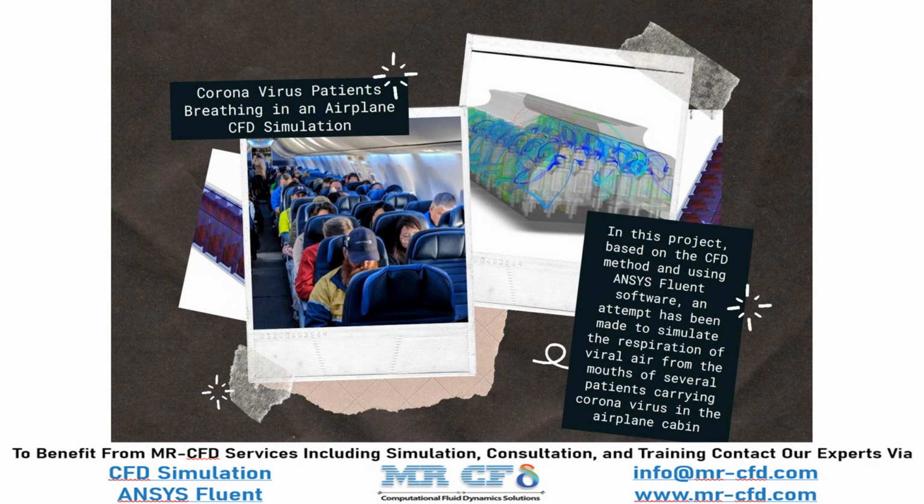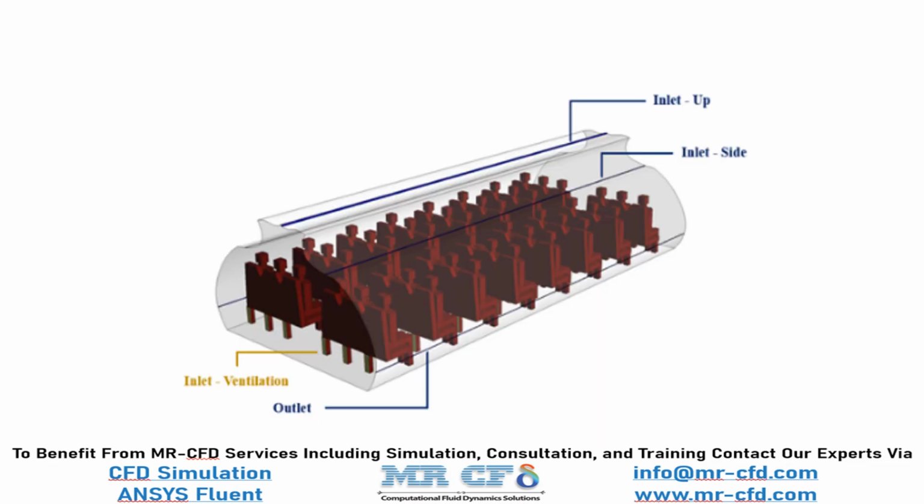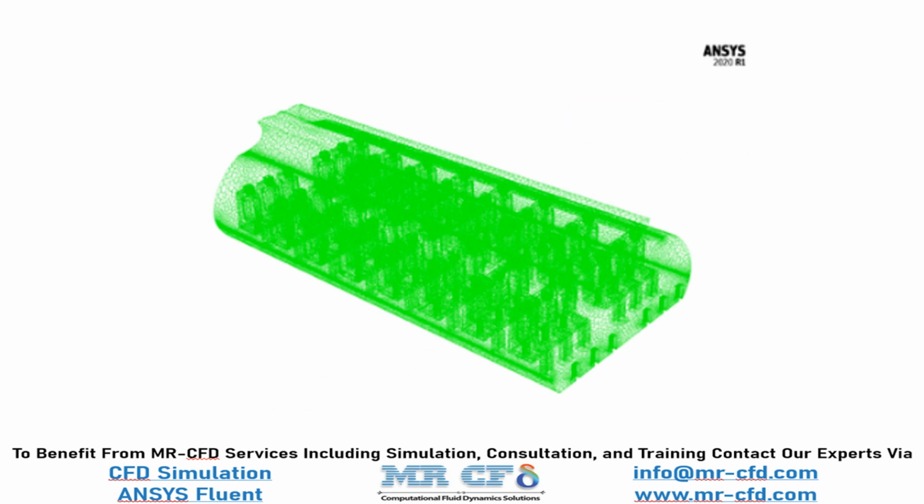We will simulate coronavirus patients breathing in an airplane using ANSYS Fluent software. The present model is designed in 3D using Design Modeler software. The meshing of the model has been done using ANSYS Meshing software, and the mesh type is unstructured.